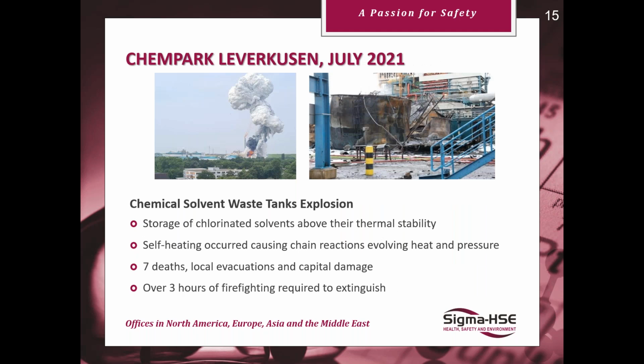And coming right up to date, just 2 years ago, so this was in Europe, 2021, they had some waste storage tanks, and this is still subject to investigation currently, but the thought is that some chlorinated solvents were added without the full information. They were then not subject to their storage requirement at certain temperatures. They just reached their decomposition temperatures, and there was a thermal runaway reaction, including explosion of the tank.